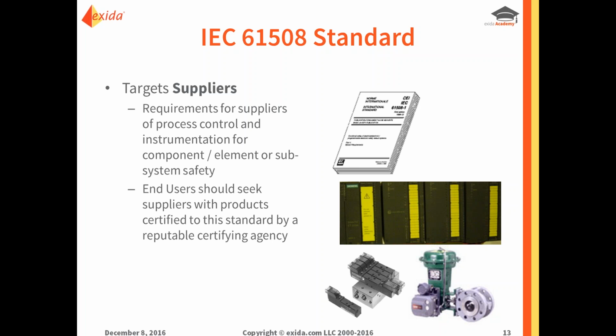It defines what functional safety is, it defines what SIL or safety integrity level is, and it defines the safety life cycle, which is very important. It says in the standard that certification is optional, but the assessment against the requirements throughout the IEC 61508 is not. So you're going to need to go through each requirement to make sure that you're qualifying from all of the requirements, but a third-party certification is not 100% necessary.